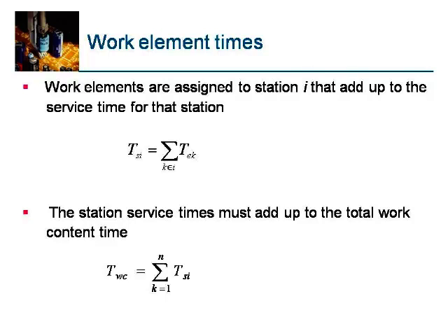Suppose the total work content is equal to 4 minutes, and you have 4 workstations. It is expected that each workstation can spend a maximum of 1 minute, and if the work elements are assigned and each takes only 1 minute, it is a perfectly balanced line. If it is not 1 minute, say one is 70 seconds and the other is taking 90 seconds, then it is called an unbalanced line, and it leads to starving and blocking phenomena, which is not desired in a typical assembly line.